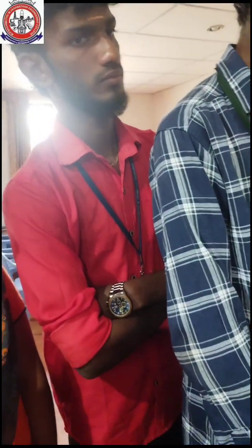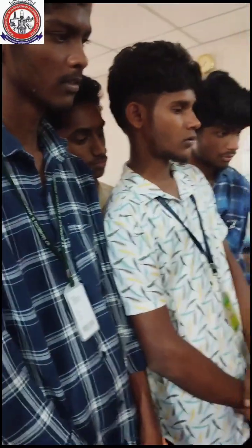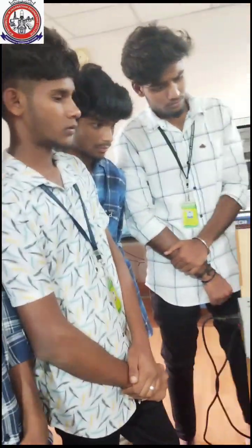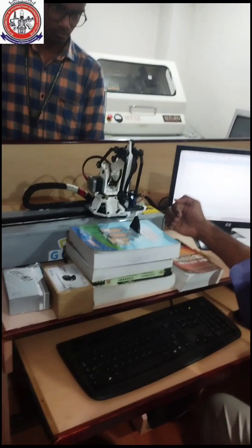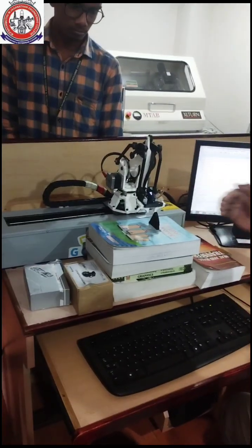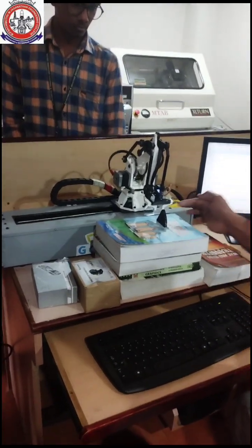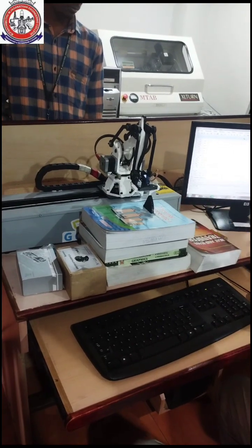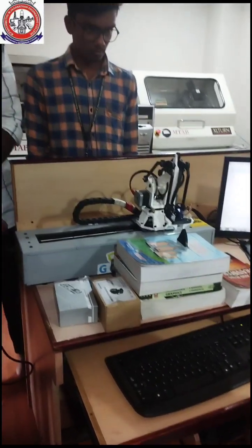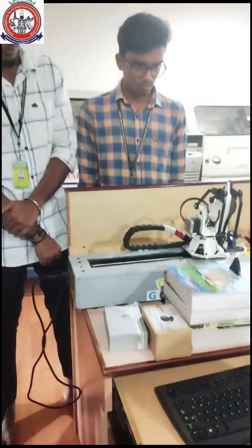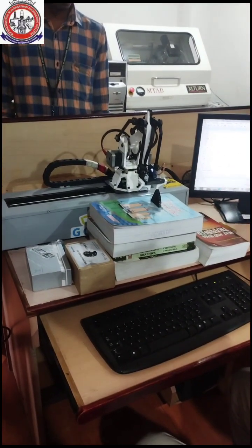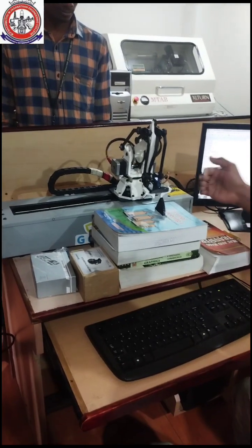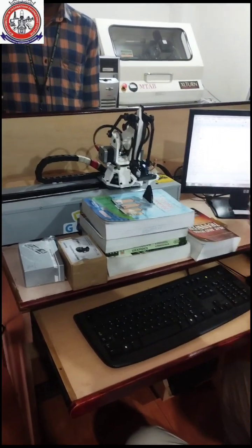This is the x axis, this is the y axis, this is the z axis. The rail is the common E axis, and the gripper is the fifth axis. Now if you give a y axis value, what about the origin of the y axis? Does it increase or decrease? The origin position of the y axis is 190. If you give 220, it will move forward.